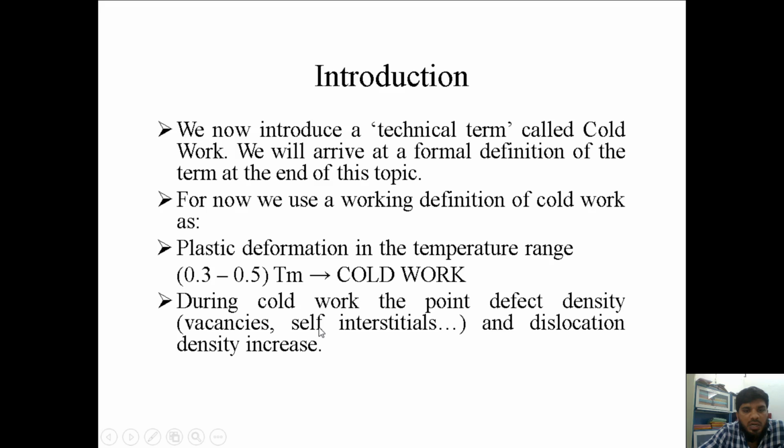If you further anneal, that is, if you are again heating and cooling it, then because of heating beyond 0.5 Tm, the crystals inside the material will try to rearrange themselves. That is what we call recrystallization, and it leads to the growth of the grains. That is the grain structure, whose grain boundaries I have shown, and the structure of the grains will change. One grain will grow from one part to the other side. So this is cold working. After cold working, if you are annealing, the material will become soft.